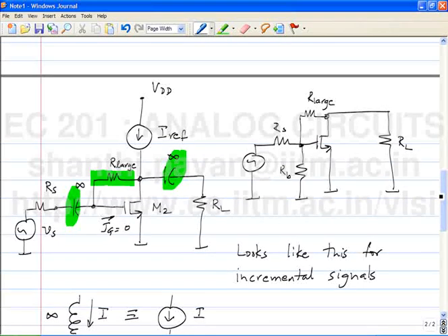you use the same transistor to fix the VGS in such a manner that the drain current remains constant and equal to IRF regardless of the value of the transistor threshold. Does that make sense? So, you can see that there are any number of ways of getting the same incremental circuit. Alright? The real circuit can look very different, but the incremental circuit can be the same. So, there are many circuits which will have the same incremental equivalent, and you already seen three.